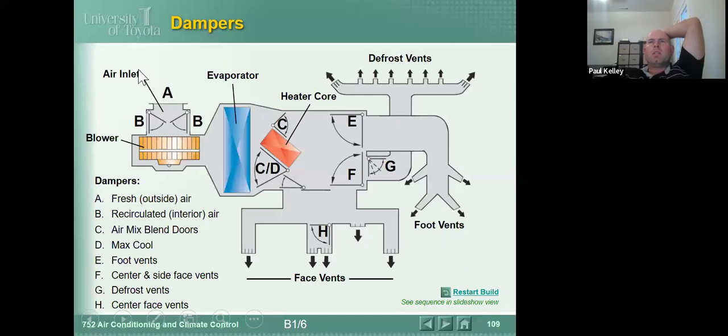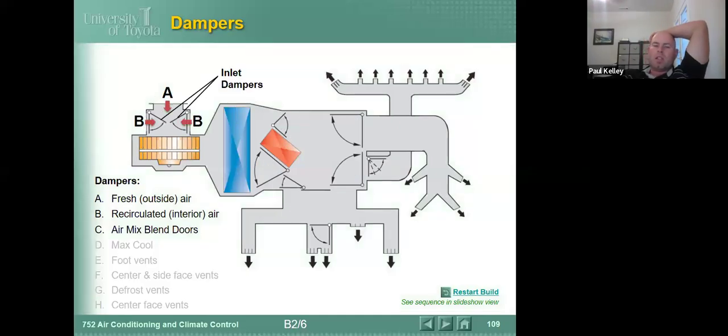So air comes in, either recirc or fresh air, goes through the evaporator, can go several different ways, depending on if it's for the passenger or the driver. Can go to these vents, floor vents, rear vents, face vent. A lot of times if a car has basic rear AC, it's just sending air under the seat. Some of the cars have cooled seats, which a lot of times has its own blower motor in the seat. But a lot of times still pulls the cool air from the regular AC. Heated seats are typically electric heat.